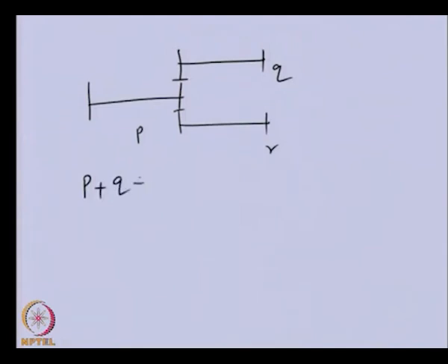degree of freedom we expect this much, but the angular displacement of branch B at this point is related with this by the gear ratio. Similarly, branch C is related with this. So, that means two angular displacements are related. So, the degree of freedom will be that much less, because we have two additional constraints.